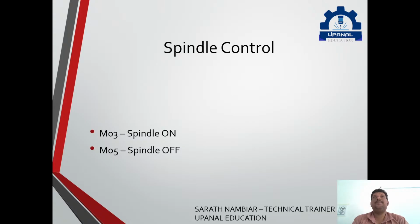That is for spindle on and spindle off. M03 will be for spindle on clockwise direction, M04 for spindle on anti-clockwise direction, of which we will mostly be using only M03. M05 is for spindle off. To turn off the spindle, we will be giving M05. So M03 is spindle on, M05 is spindle off.